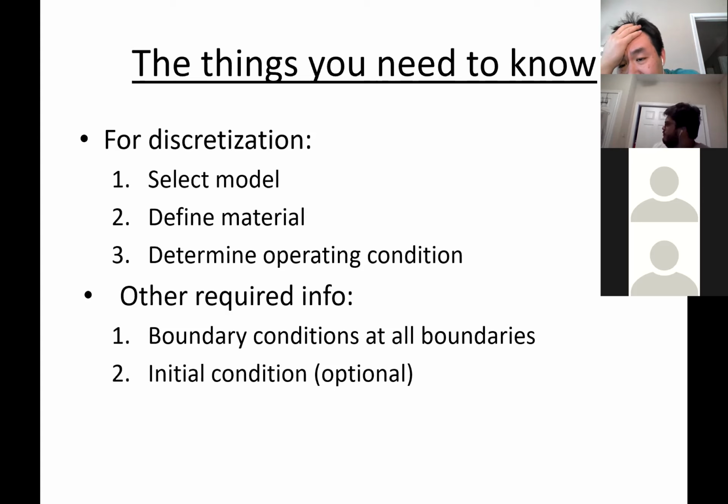Here it's similar, okay? You have a 3D space you want to simulate. The entire boundaries enclose that 3D space. You need to specify the boundary conditions on every boundary. You can't miss anything. If you miss any boundary surface, it's a non-closure. That won't give you any solution. You won't be able to solve. Okay, keep this in mind.